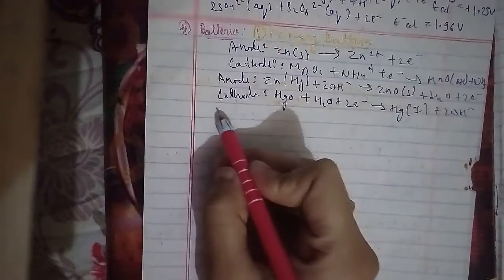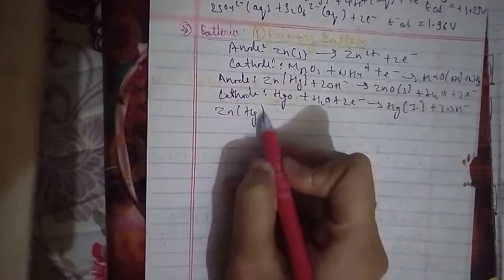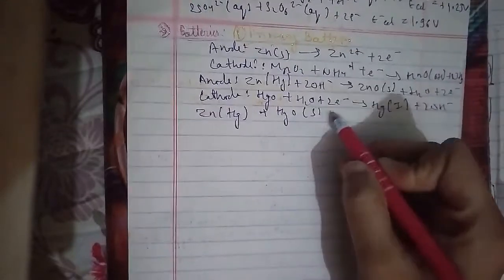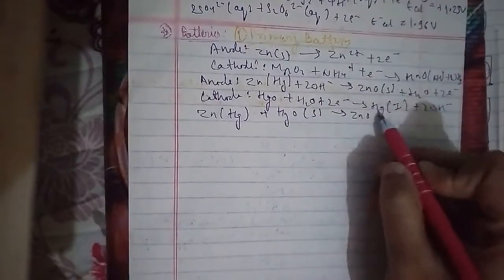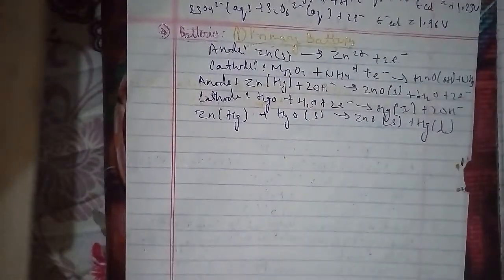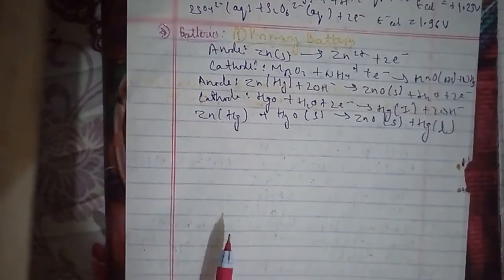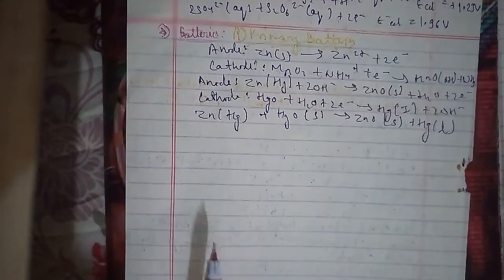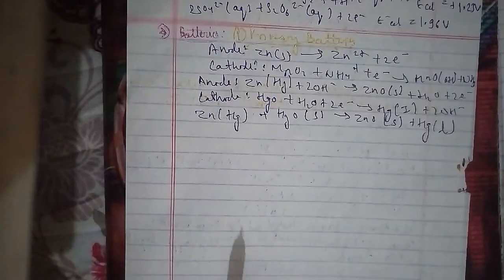Here the cell potential is approximately 1.35 volt and remains constant during its life, as the overall reaction does not involve any ion in solution whose concentration can change during its lifetime. The cell has a separator, a cathode, a gasket, the cell can, anode cap, and anode. Next we will discuss the secondary batteries, which are also important.